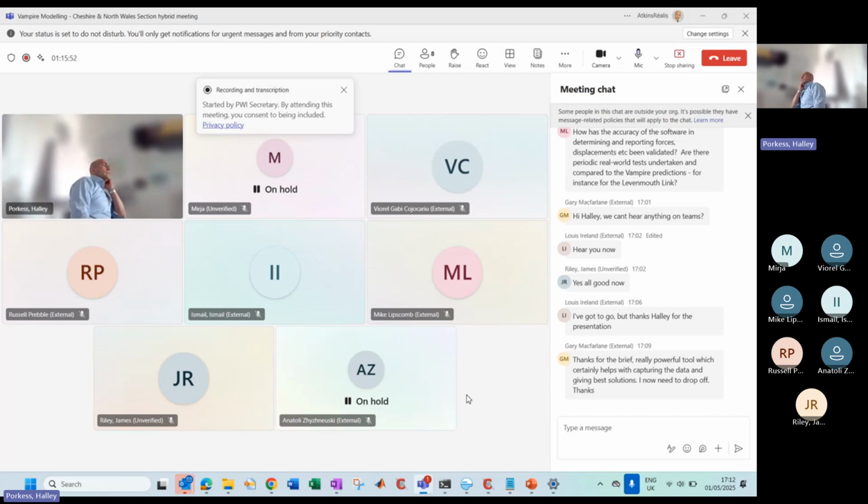We've got time. I was just thinking about the derailment risk assessment, could you use that to prove whether or not you needed guardrails, collector rails on viaducts as well? Or is that something you just have to do because the standards say so? My understanding is you need to have them because it's about trying to contain a train that's already derailed. There's a subjective assessment we need to do first to say whether you think you need them. Do you always need the collector rails? Sometimes they aren't there. You want collector rails if you're facing, going off the end, that's my opinion anyway. I think both ends.